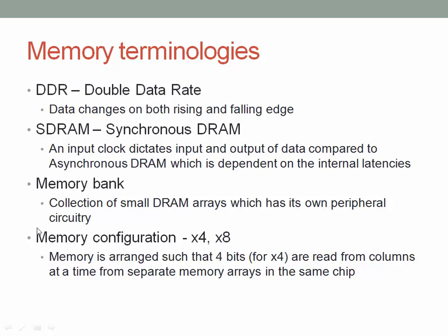And so memory is configured as X4 or X8 parts, or it can be any other number. So that means that when there is a read command which is given to the chip, there are that many bits or words which are read out from the chip. So for a X4 part, there are 4 bits which are read out at once.